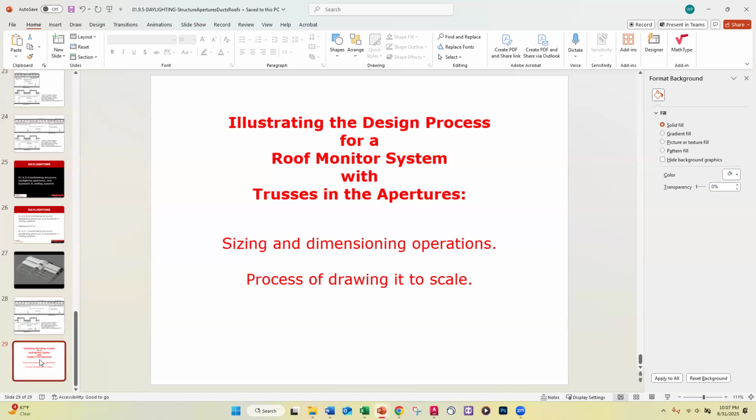So you're going to start practicing sizing the glazing, sizing the curb height to accommodate the water, accounting for the slope of the lower roof in order to make sure you have positive runoff of the water. The longer the bay, the greater the vertical change between the high end of the sloped portion of the roof and the low end of the sloped portion of the roof.